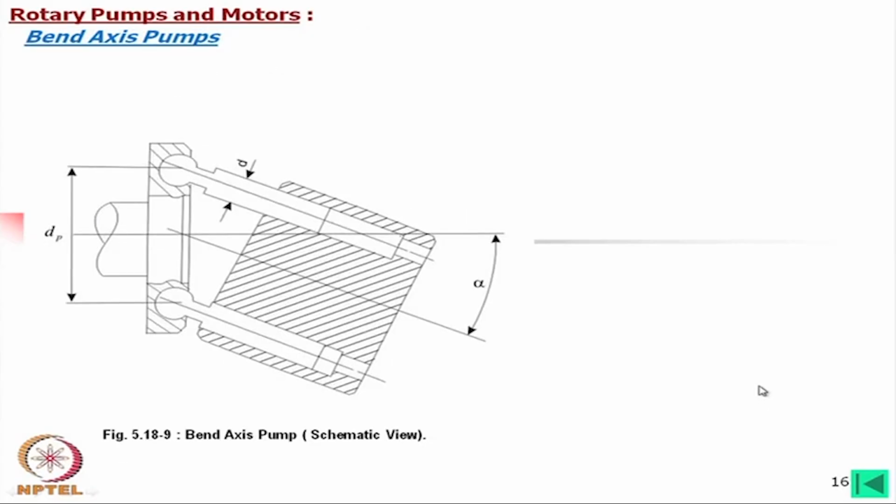Now, usually in the swash plate type piston pump which I have discussed, the alpha angle, which is the tilt, is normally around 20 degrees, precisely 21 degrees is a good value which is commonly used, but that is the maximum. We cannot make it more.